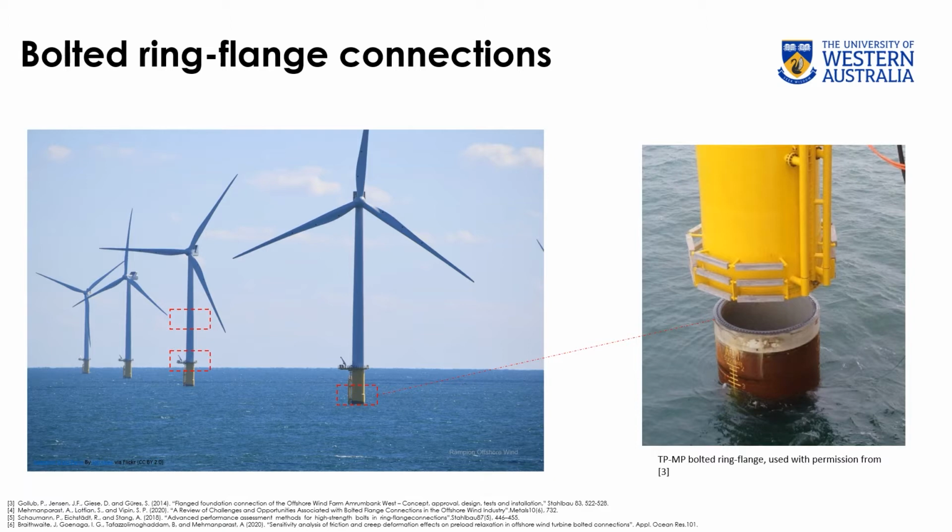One of the primary concerns when designing the overall offshore wind turbine structure is fatigue lifetime. Schaumann and co-authors in their 2018 paper suggest more than 1 billion load cycles are possible. Literature in the space also records flange alignment, see again the paper from Schaumann and co-authors from 2018, and bolt preload, see Brathwaite and co-authors from 2020, as significant considerations in fatigue design.